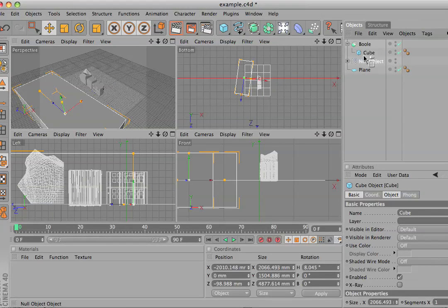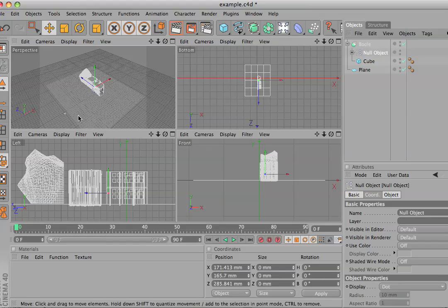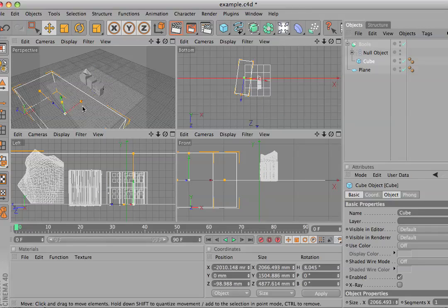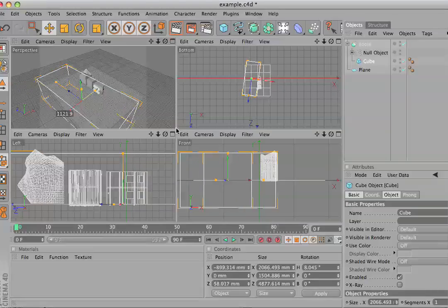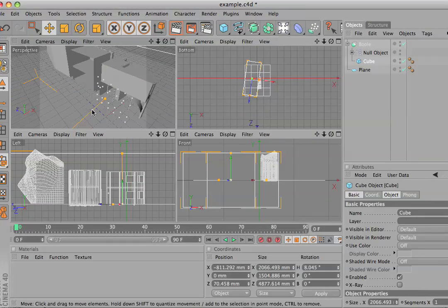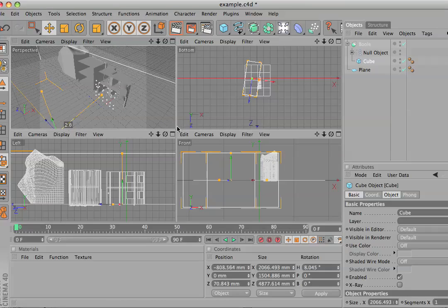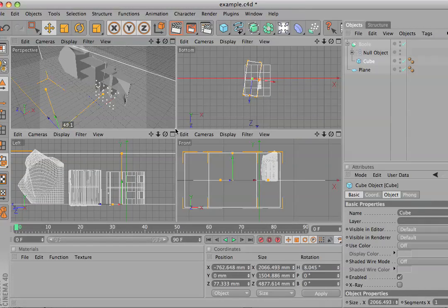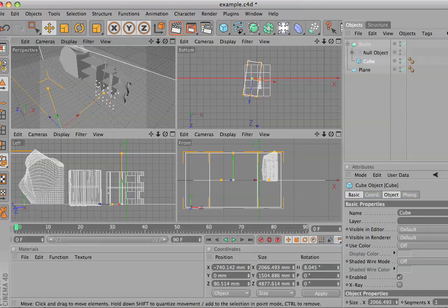So you need to have a cube in the scene which is big enough to intersect all objects you're going to section. So by moving it onto the objects, you create your section of the scene. Obviously we've left the plane because we're not sectioning that.